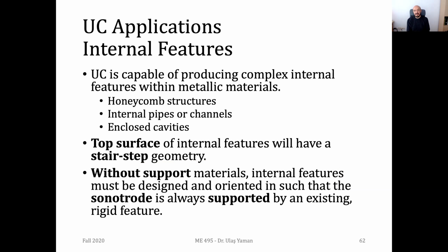Another issue, we discussed it at the beginning of the lecture today. Once you have wider internal channels, you should be careful about the force you are applying with the sonotrode. If it's too much, then you cannot have a rigid feature. Probably there will be some kind of bending, and your internal features will be modified. You cannot have a perfect shape.